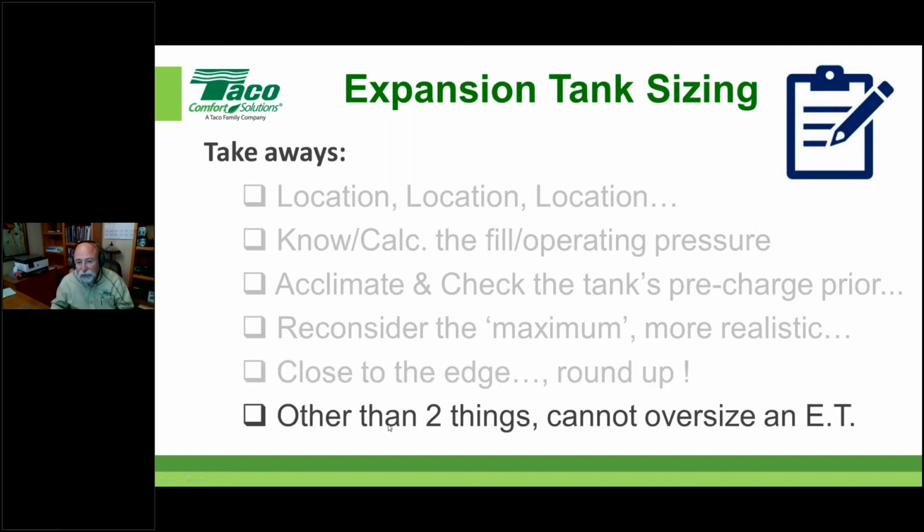And basically that closes these. There's 2 things about an expansion tank. Okay. As far as the real estate that it takes up. Okay, depending on what size it is, it's going to eat up some real estate. Okay, and the price that you have to pay for it. Other than those two things, okay, you can't oversize an expansion tank.